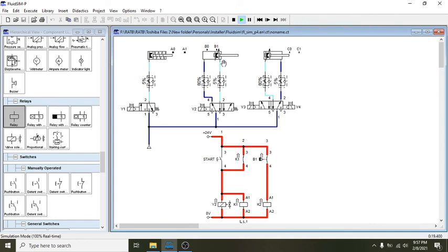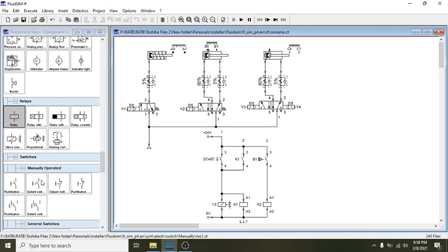After this, the cylinder must be able to return to its retracted state. So it must retract automatically. To retract, we need to turn off this coil. How do we do that? We can make use of the contact of the relay, the normally closed contact.